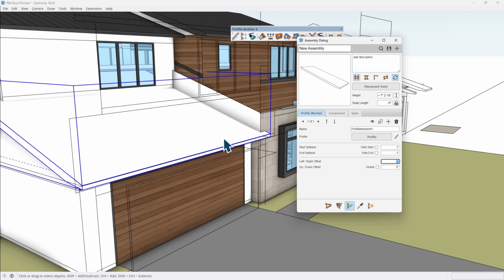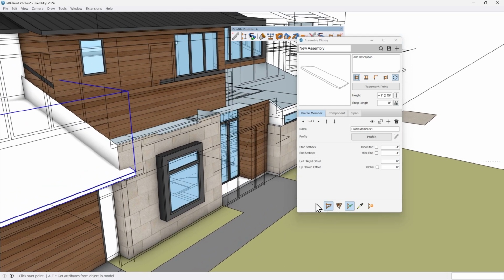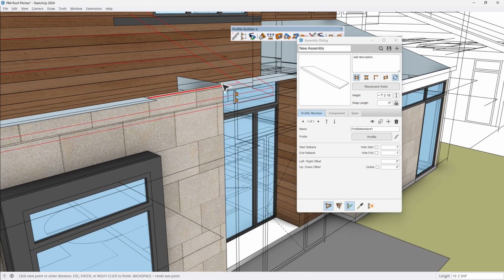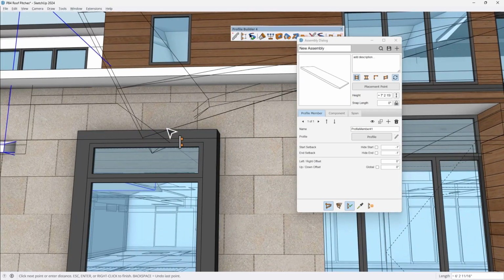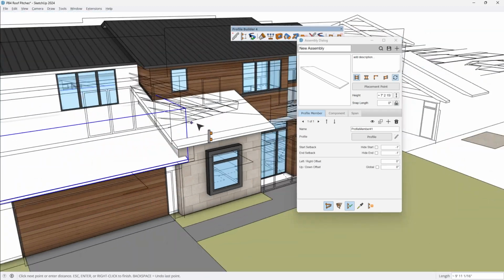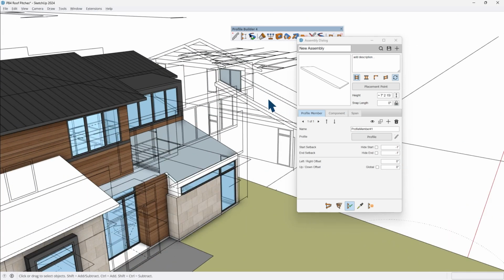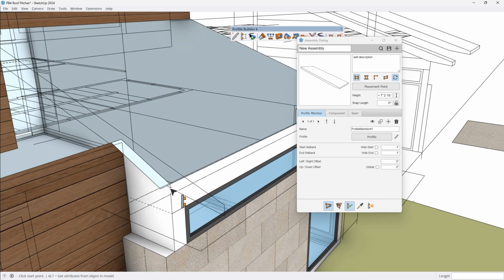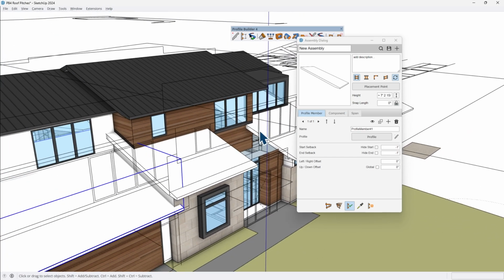So now what's really cool with this is I can just continue building, right? So I can click build assembly and find the point that I'm drawing from, which is going to be here, pull that over to the far side there, and it's building in that extension. And now what you'll see with this particular file is the piece that I traced from is the longest assembly. And there's a reason for that. If I use the longest assembly, then I can easily carve away at the parts that I don't need.